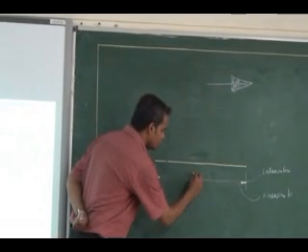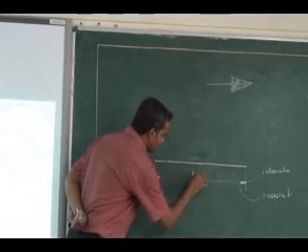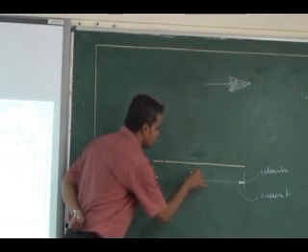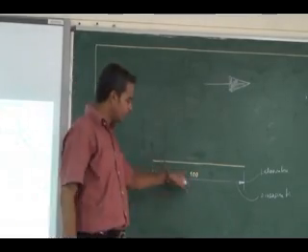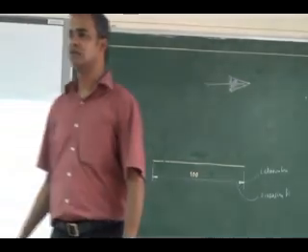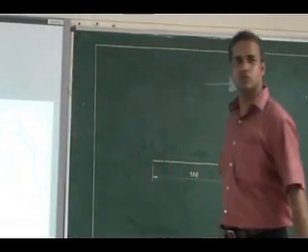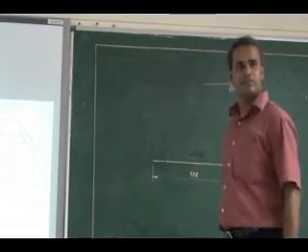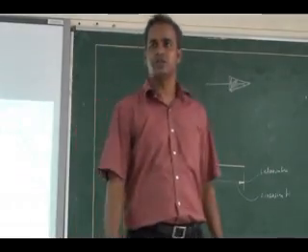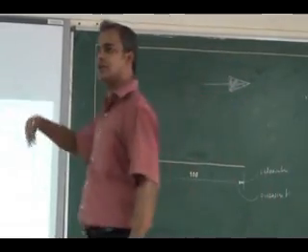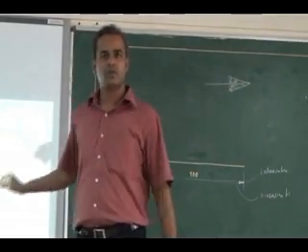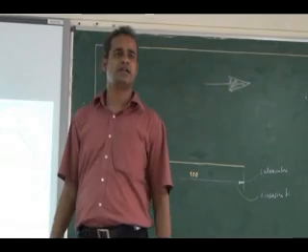In the middle, I can write 100 as per your lettering standards. This 100 should not touch your dimension line. It should have a little bit of gap. Right. So I have two methods: aligned system and unidirectional method. In the aligned system, the values are aligned and placed over the dimension line. In unidirectional, the values which you are writing in dimensions